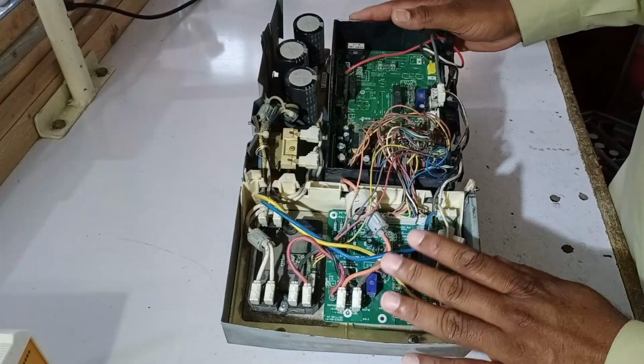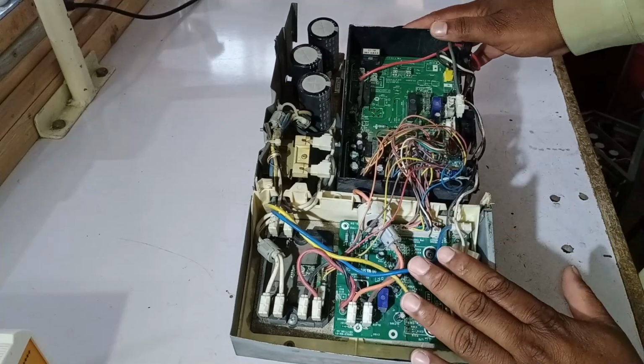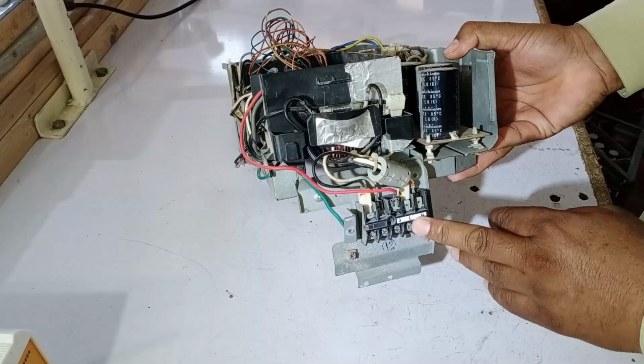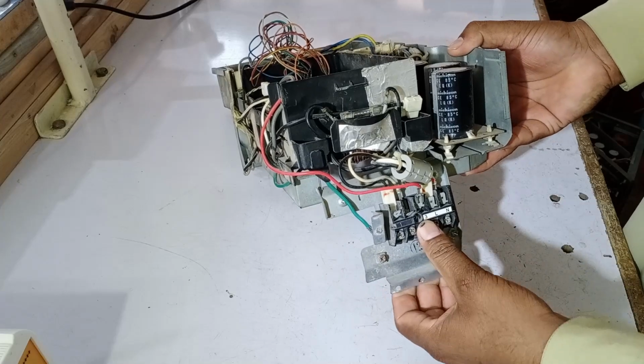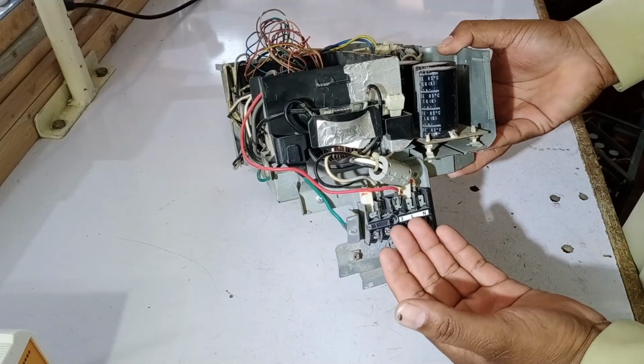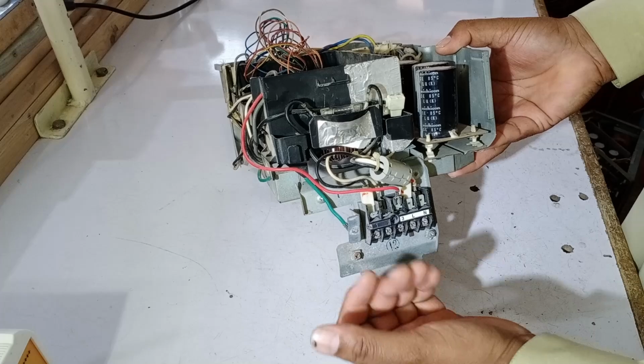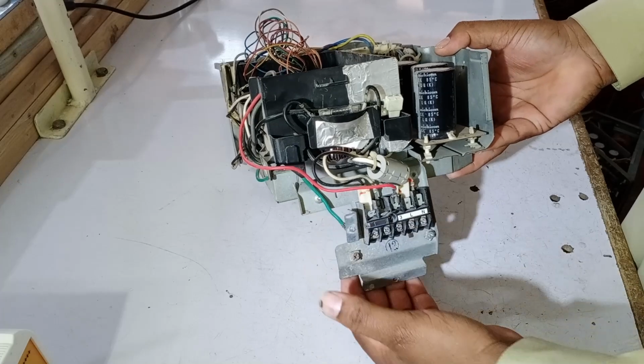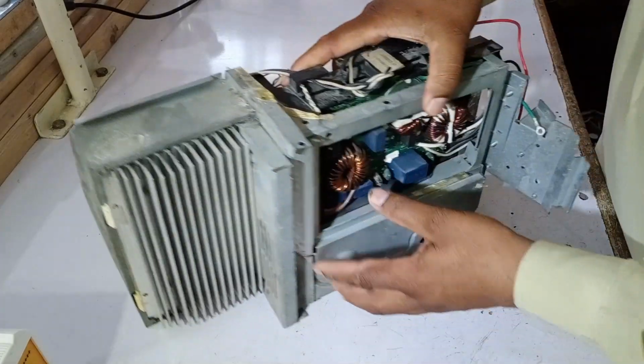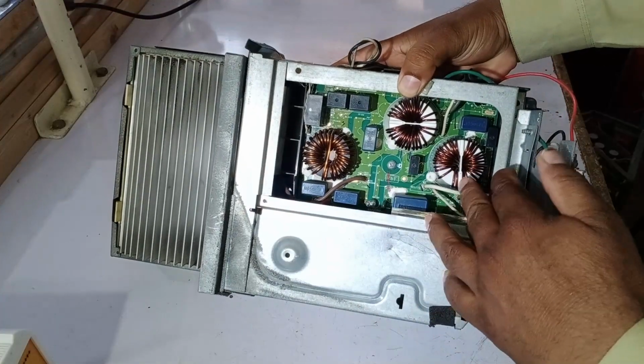Now let me explain how the 2.5-ton and 3-ton units operate. They use the same system, where electricity flows from the outdoor unit to the indoor unit. Because of this, it's crucial to check the communication wires and other electrical connections to ensure no wires are burnt or cut. Step 1. Checking power PCB and rectification.